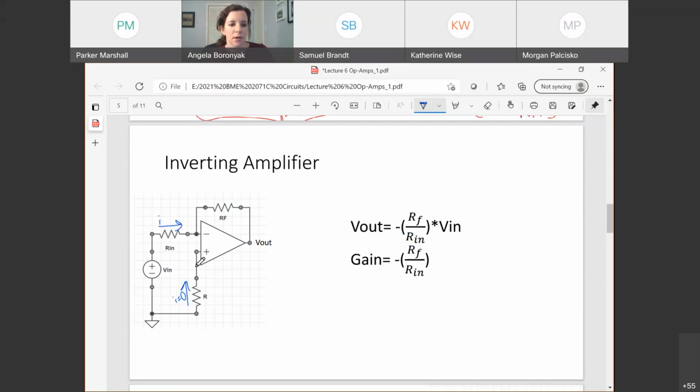If this current is 0, my voltage down here is what? On this wire, what am I at down here? What did I call that voltage? Ground, or 0 volts, right? If I have no current through a resistor, so I is 0, what's your voltage drop across that resistor? What's delta V? Also 0. No current, no voltage drop across a resistor.